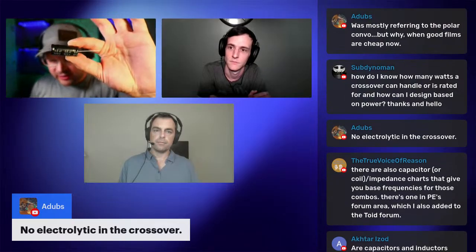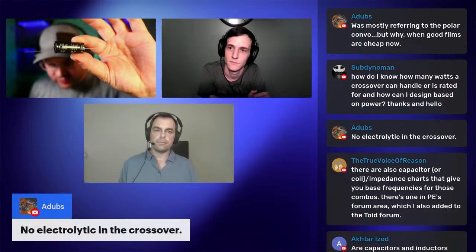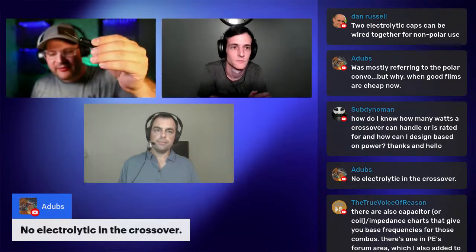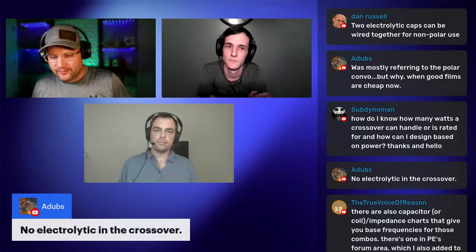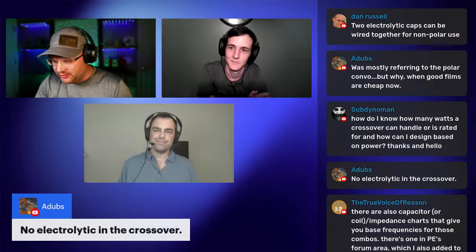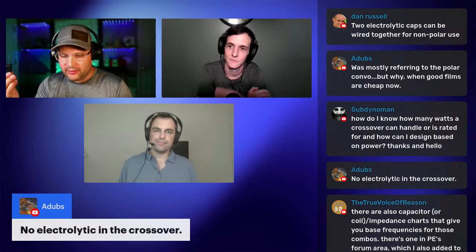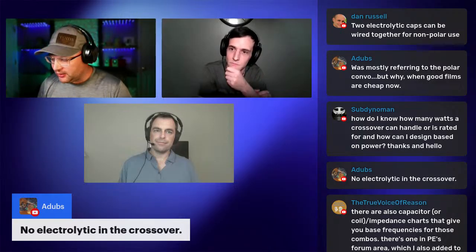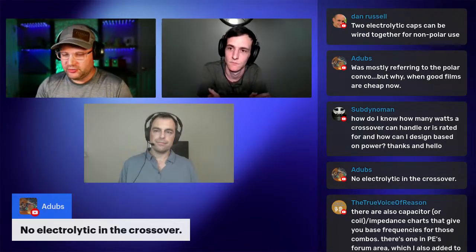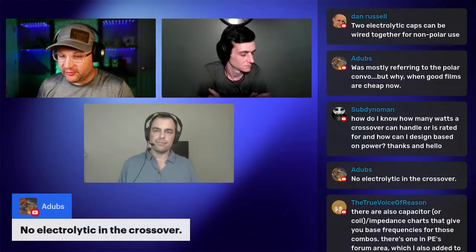Now this is an electrolytic. It looks different. It's gray. It's a big value, 68 uF. I only use electrolytic in two situations: cheap speakers, like small desktop speakers, or if they're going to ground. When they're going to ground, I use electrolytic because it doesn't matter nearly as much. But sometimes you need a large value capacitor, and electrolytics are much cheaper for large values.